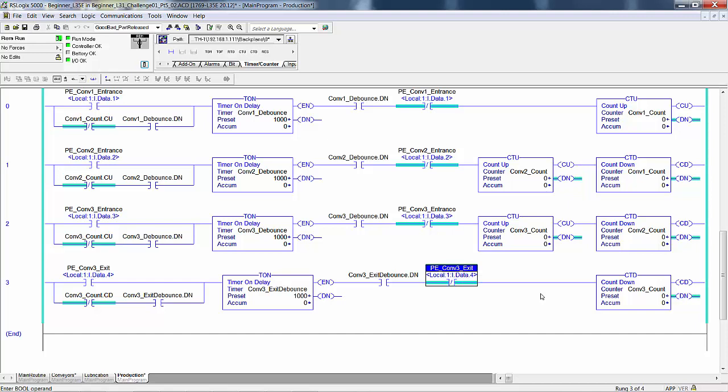Now here's a thing that you can do to your code that protects against a negative number. Now if you had this running in a system and somebody walked by and put their hand in there and you had more, you had say 2 in here, 3 in there, I mean you can't protect the system from that kind of superfluous behavior by employees. It's just not possible. But you can prevent a negative count by putting in a greater than 0 on the count.